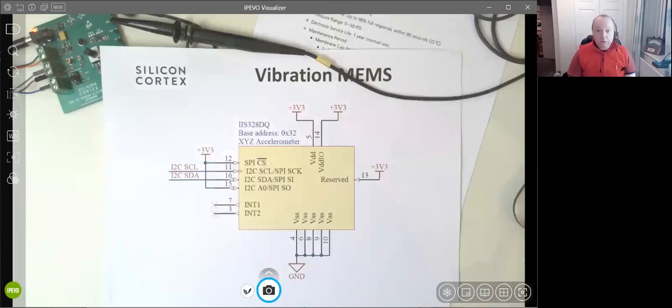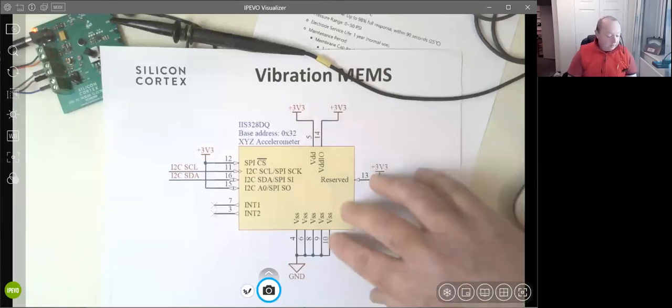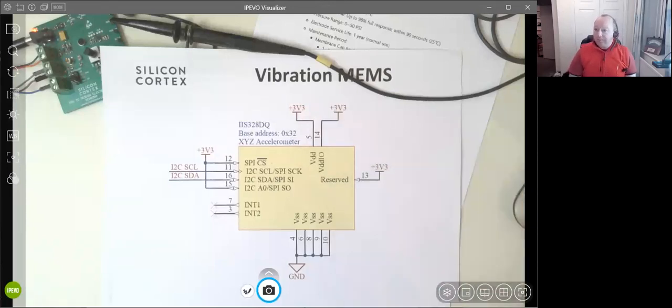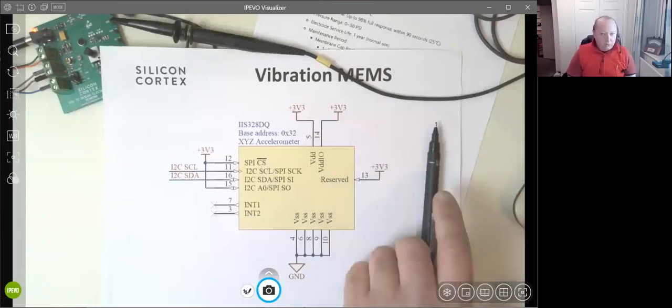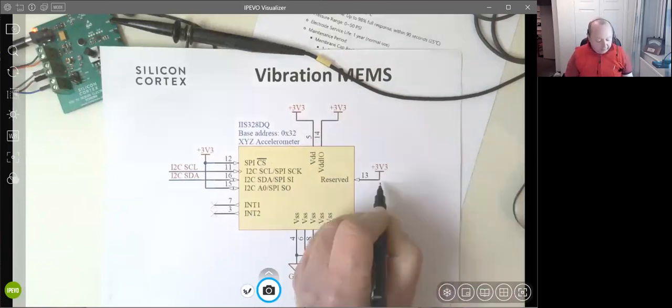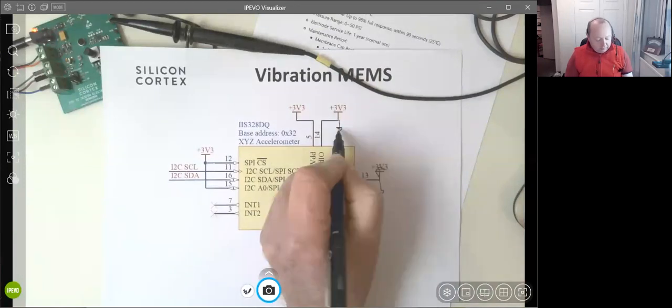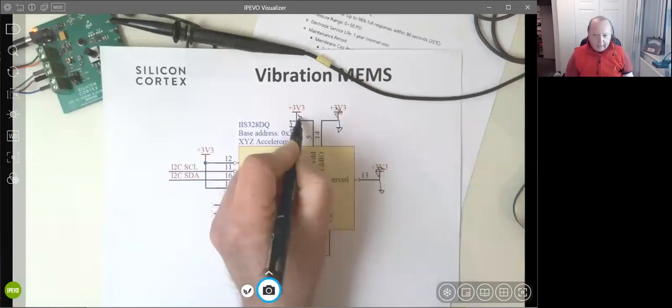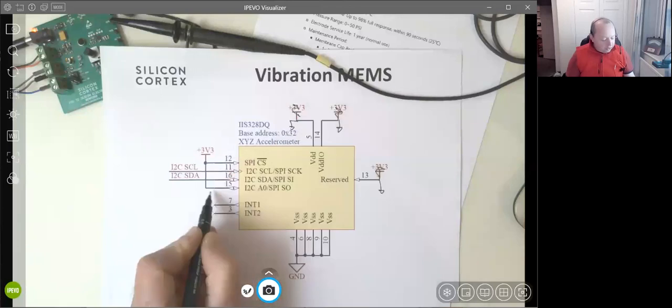But the big challenge, of course, with accelerometers, which we haven't discussed, is something called Stiction, which essentially means no one's quite sure what causes it. I think it's electrostatics in the microengineering, that basically the mechanical system just locks and gets stuck. And the only way you can free it is if you just tie everything to ground. So almost like a 100% discharge.